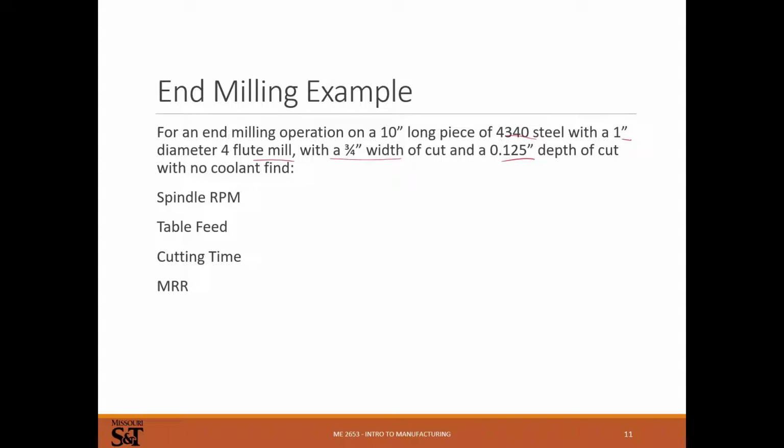That's the only part that's going to get dull, and that's why really for face milling like this, you want to use a face mill that's designed for this. Face milling with an end mill doesn't make a lot of sense, because you're only getting the very bottom of the cutter dull, and when you scrap your tool, you have a whole lot of cutting edge that you never use. That's something you want to avoid.